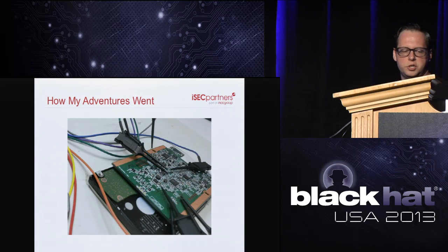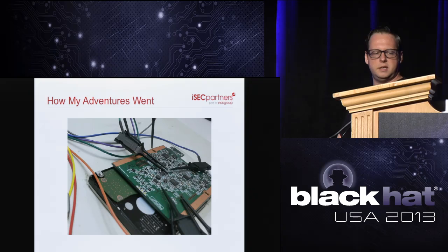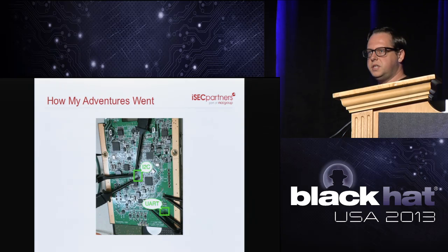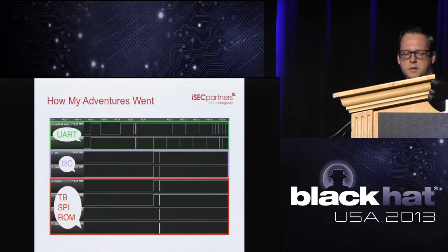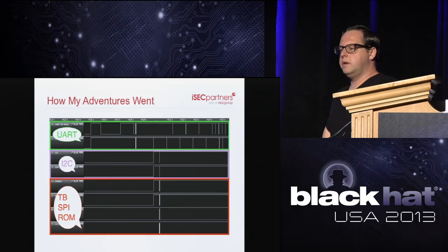Once our wires are soldered in and our epoxy set up to protect it, we can start sniffing the board and sniffing all the traffic on there. Notice our I2C connection being sniffed, and also our UART connection at the bottom into our ARM Cortex from our Apple. So here's an image of the output of the logic analyzer.